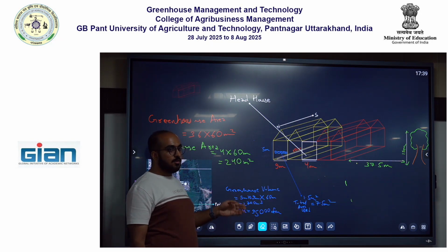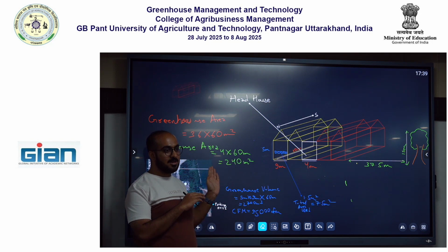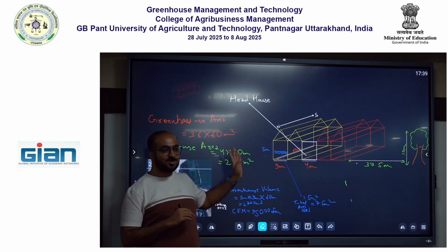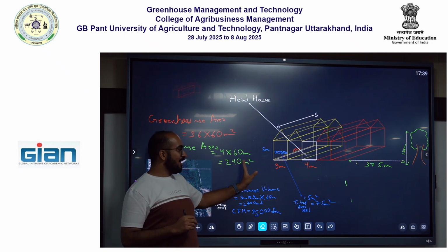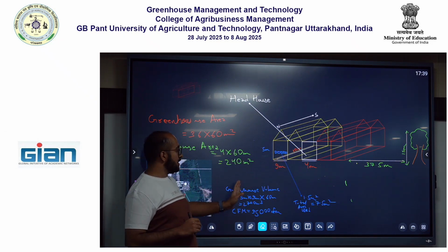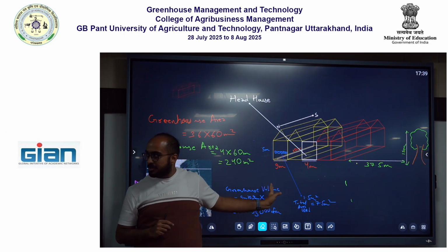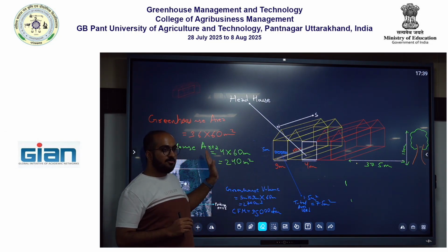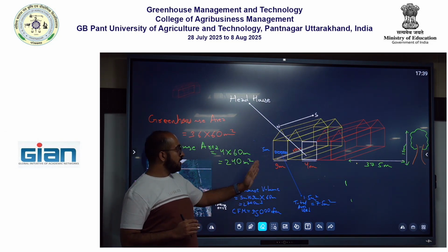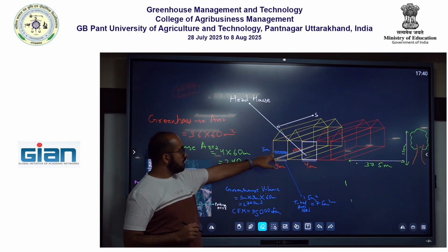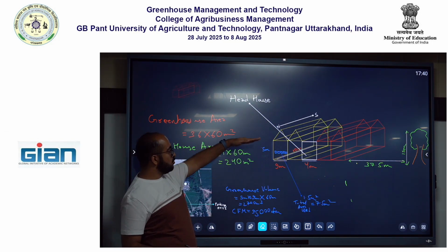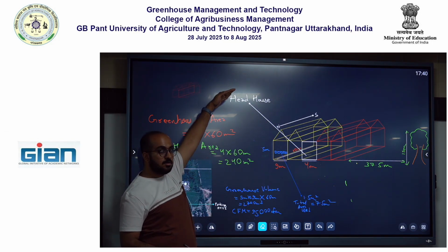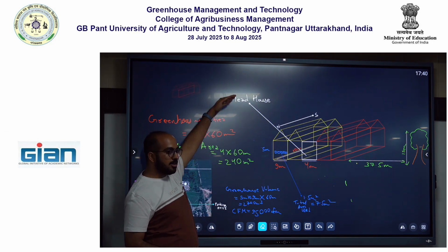We checked the fan sizes available in the market. This is the biggest fan size we have used, and we have around 5 fans fitted 0.5 meter apart from each other, with 0.5 meter from both walls as well. They are at a height above 2 meters, 1.5 meters from the bottom and the top as well.